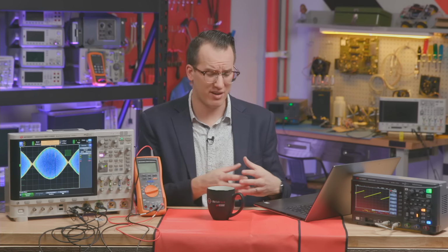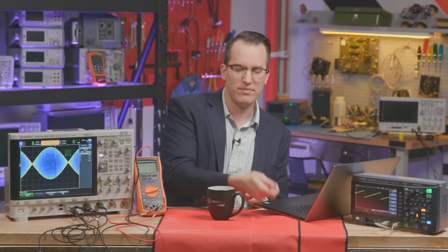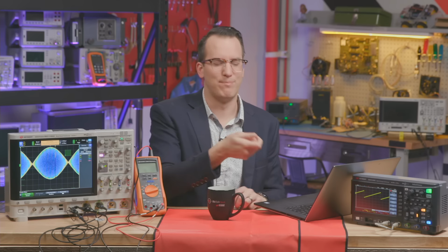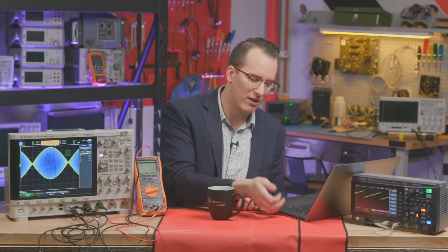We talked a little bit about probe loading on Monday as well, but essentially there's an inductive and capacitive load, mostly capacitive, when you hook up test equipment to your designs. Being able to reduce that is the reason a lot of people, especially on higher end systems, buy fancy probes to test their system, because you don't want to break your oscillator or mess up your transmission lines or communication lines when you go to probe it. So we recommend using 1x, especially for measuring things like power rails.